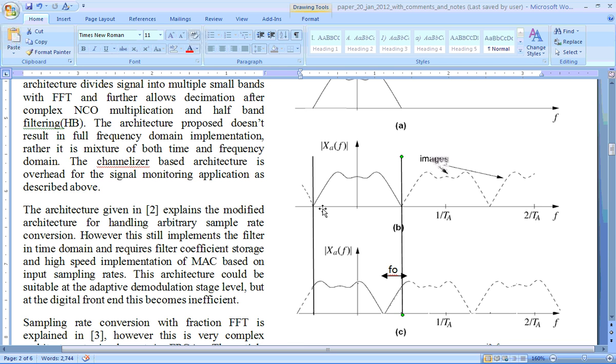When you say 1K point FFT, you have only 1024 frequency domain samples. So out of these 1024 samples, the few samples which are going out are entering over here. If you achieve a rotation within the 1024 samples, you will get the spectrum back, isn't it? Whatever is going out here enters on this side. So among these 1024, it is like a rotation. That's all.